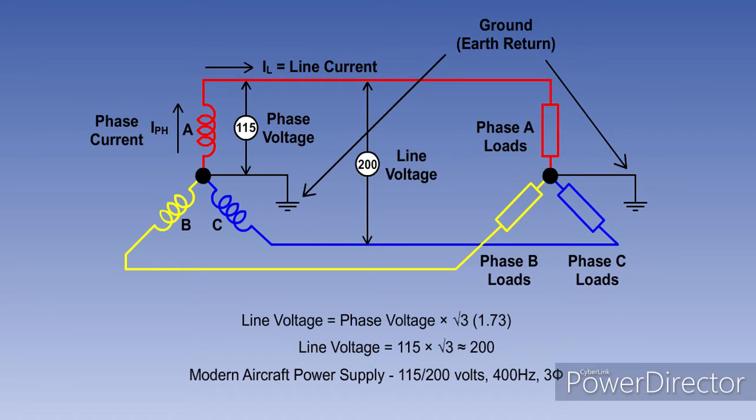While the voltages of line and phase differ in the star-connected system, because the windings form only one path for current flow between phases, the current flowing in the lines will be the same as the current flowing in the phase windings. Thus line current equals phase current.